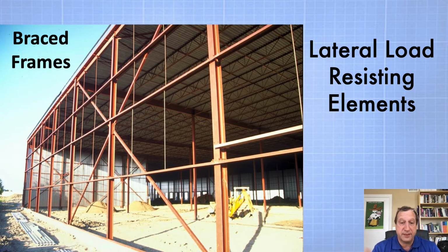In this case, I think they were 75 or 90 millimeter angles by 6 millimeters. And that X brace you see goes through the column at the middle, and that helps so that the part of the X brace that goes into compression when a load is applied doesn't buckle as much out of the way before those tension connectors kick right in.